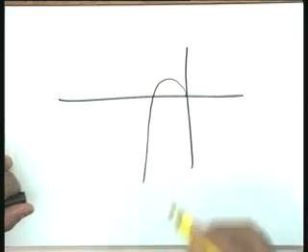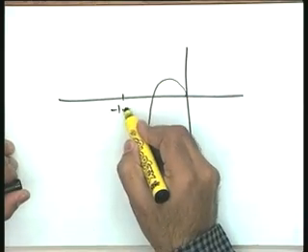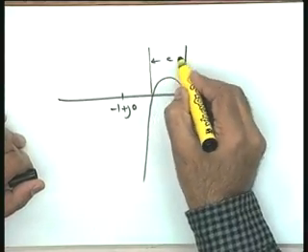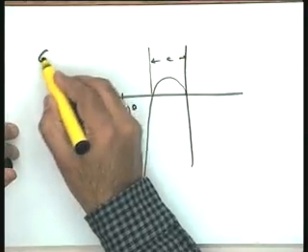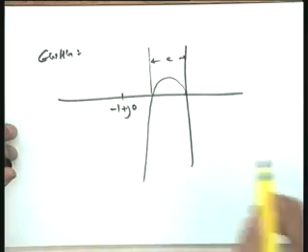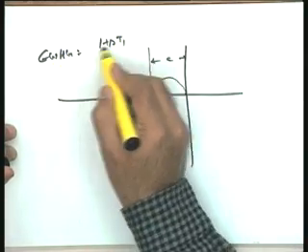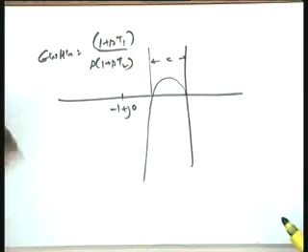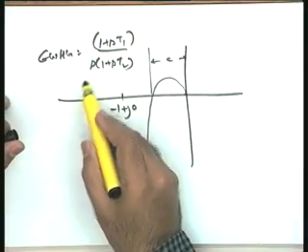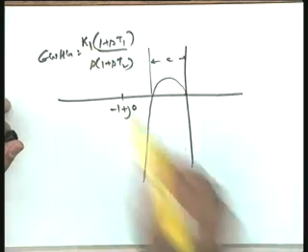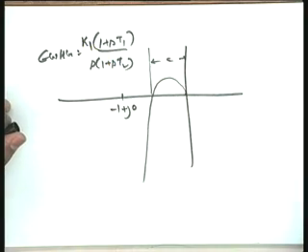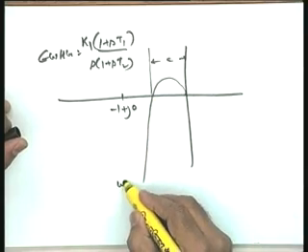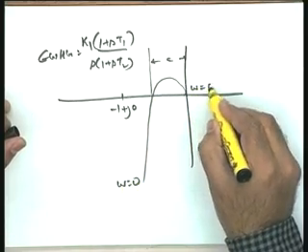This was a typical plot I am taking, all the specific points I will answer later. You see, this is the point, this is the magnitude A, and let us say that this plot corresponds to G(s)H(s) equal to (1 + sT1) over s(1 + sT2), some function I have taken, okay. You can take even some k1 over s(1 + sT2) as the transfer function for which the polar plot is given to you, omega equal to 0 to omega equal to infinity.